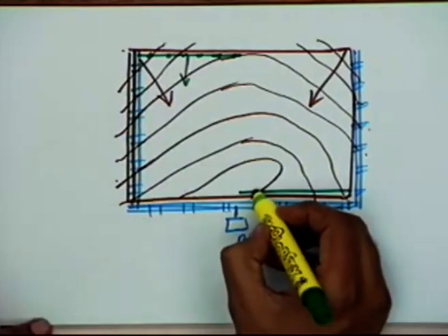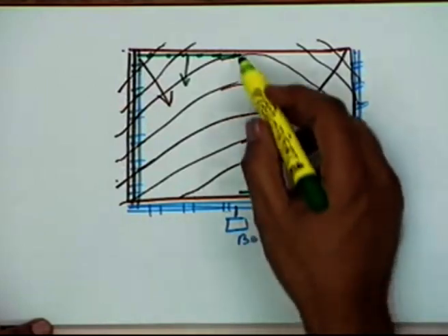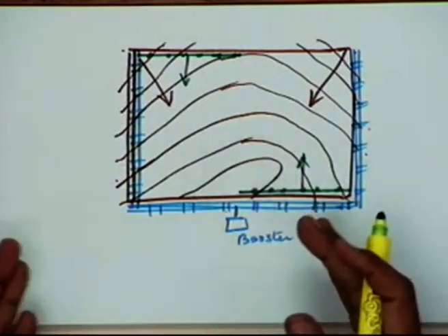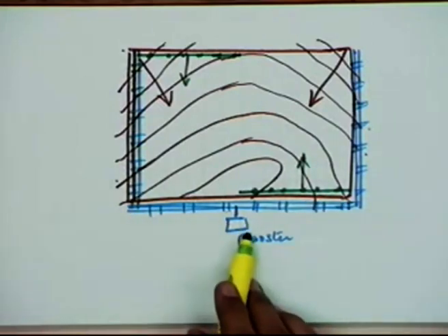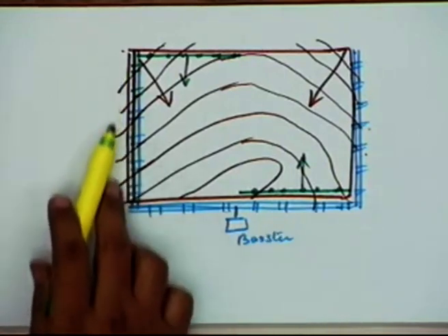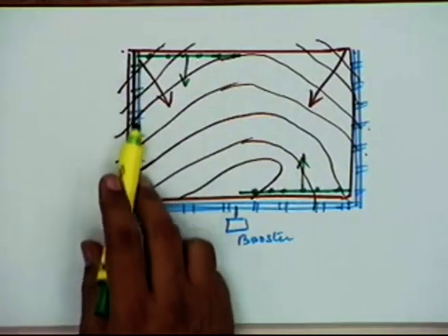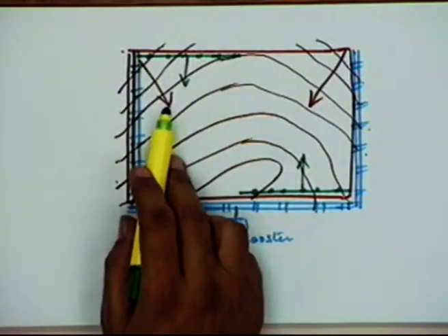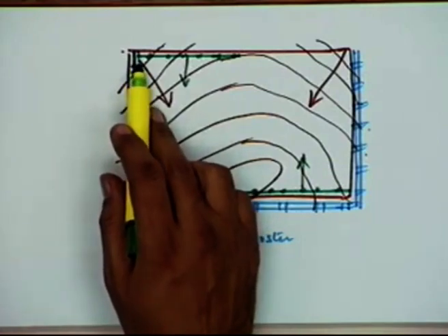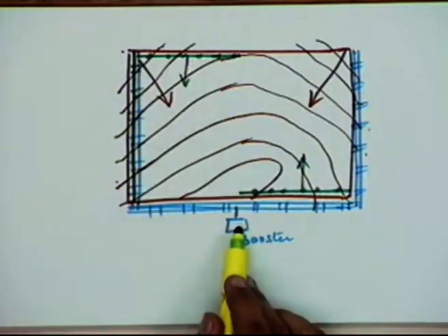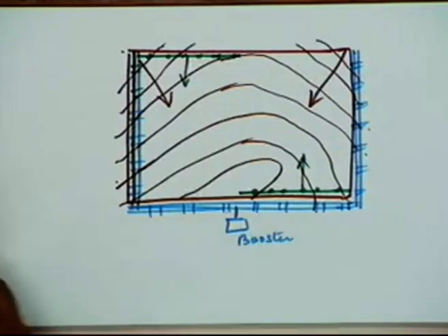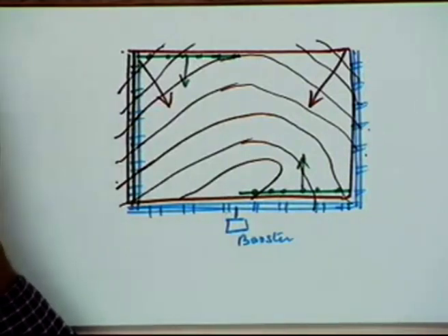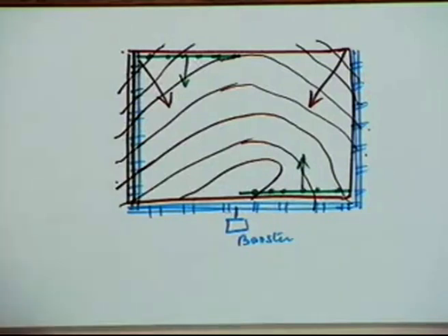As far as the lateral is concerned, you can have the lateral which is taking care of the other half of the field, and this lateral you can move up. So this is one way of covering this area, in which instead of having a very high pressure in this section of the line, because in that case, as we had discussed earlier, if you have very excessive pressures, they might be detrimental as far as the pressure in these laterals is concerned. So either you will have to use some device by which you can control the pressure, regulators have to be used, or you can go in for a booster, which is a much better option than providing excessive pressure and then bringing them down through the pressure regulators, because providing the pressure regulators increases the cost.